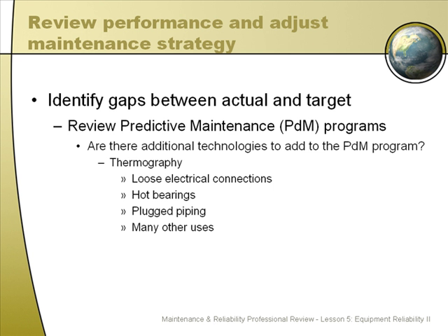Another excellent PDM program tool is thermography. Basically, it's the use of the infrared spectrum to look at equipment and processes to find defects. It's very useful and traditionally used to look for loose electrical connections inside of cabinets and inside buswork. Second, it's very useful for looking for hot bearings and different surfaces on equipment. Another thing that it's very useful for in processes that use piping is looking for plugged sections of piping and also bridging inside of tanks and things of that nature.